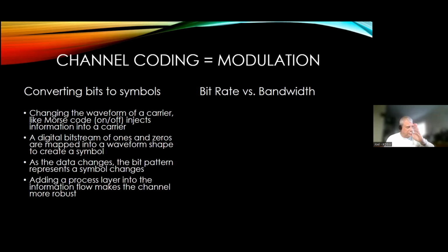And the more Gaussian the wave slope is, the fewer key clicks and the narrower the bandwidth. So if it's a very steep slope, not much like a sine wave but much more square wave-ish, then you're going to create more sideband energy. And that's what we don't want.